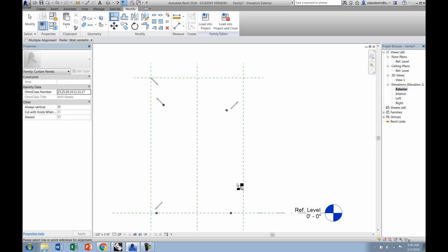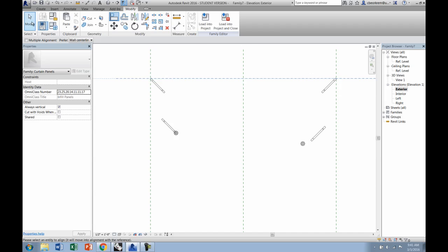The way to figure this out is if I select this edge to align to, you can see the ones that will allow me to snap to one of the vertical references, and this is that strong reference line that we gave it, is allowing me to select it. So that one actually belongs on this face, and then when I select the top, you're going to see that it gives me the option to select the top. I want to make sure and hit the lock button each time I do that to get these guys snapped to the appropriate sides. So I'm going to select this guy.